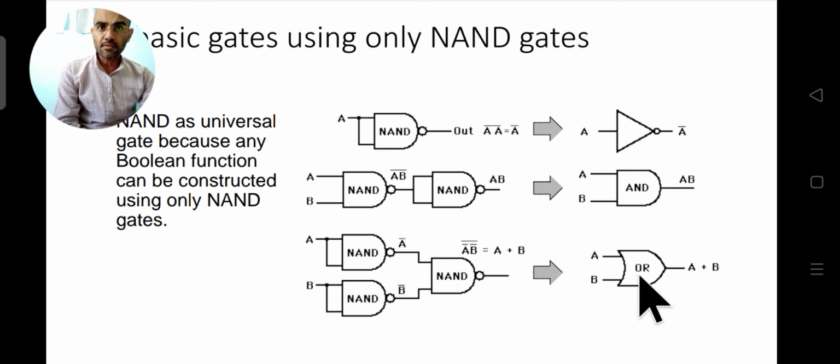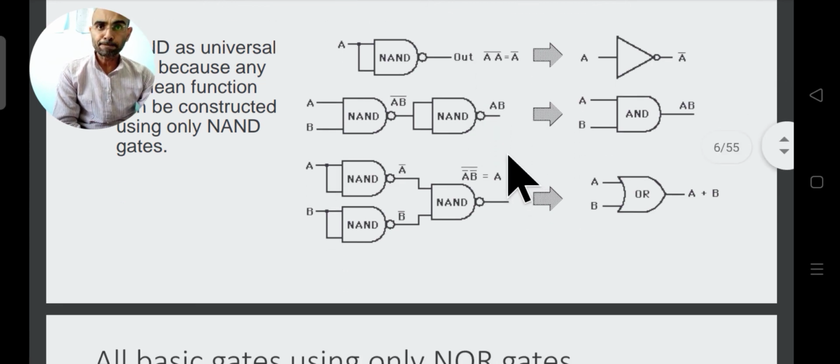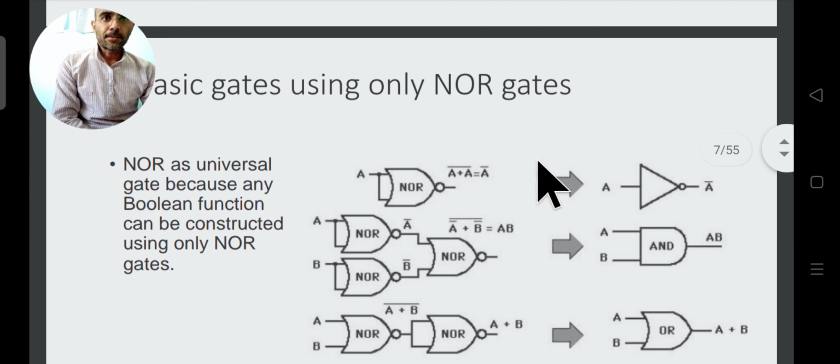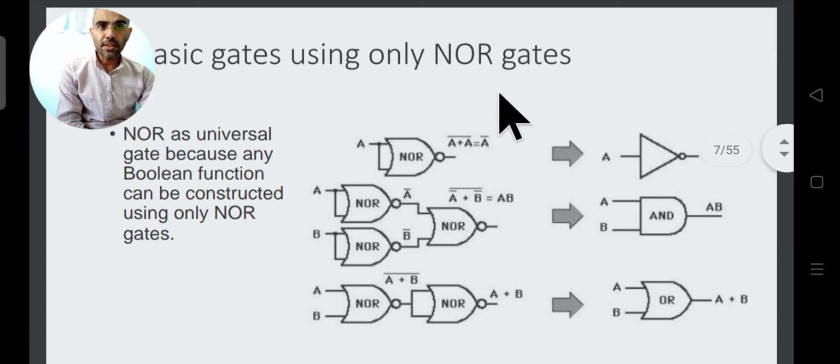If you remember this, things will be very easy for you to convert a given AND, OR, NOT circuit, that is the circuit which is implemented with the help of basic gates AND, OR and NOT. This type of circuits are usually called AOI circuits. You can implement these circuits with the help of NAND gates or NOR gates if you remember this.